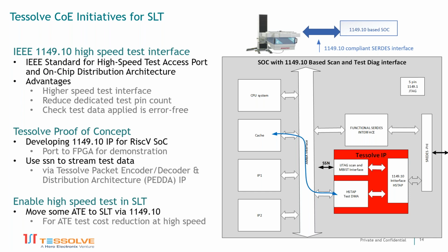So I don't think they'd move all of the testing in there, because then you'd be binning high numbers of chips that have been packaged, and you'd be losing that package cost. So I'm not sure they're going to move everything in there, but there's a potential cost saving as long as you're not having to bin too many packaged chips.